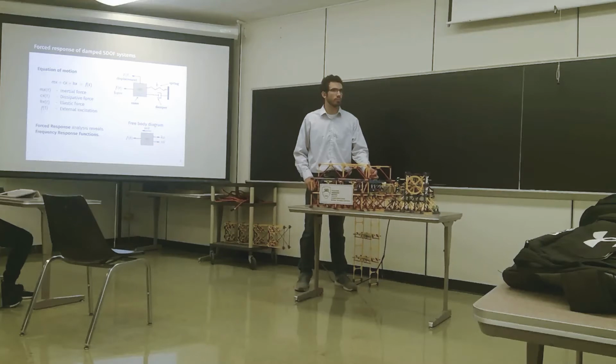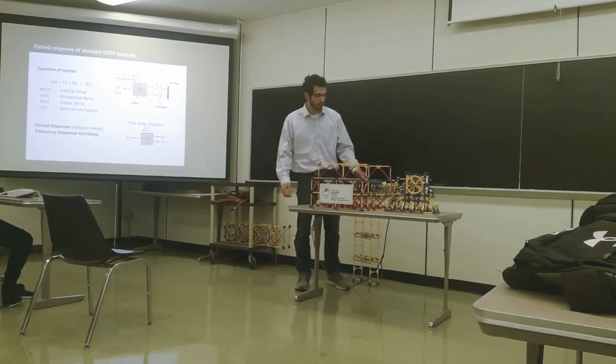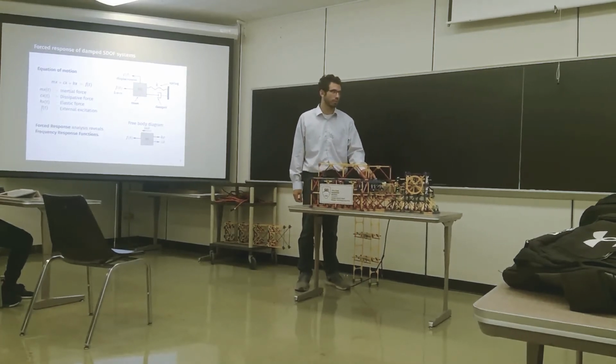And you were saying concrete increases. How does that work again? You mentioned a word, but I didn't recognize it. Have you ever worked with superglue? Yeah, a little bit. Okay, what happens? Initially, it's sticky, right? Yeah. But if you leave it over time, its strength increases? Yeah, it solidifies. That's what is called curing. Concrete also has a similar thing, but it takes a much longer time for it to cure.